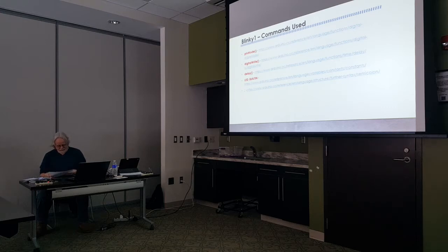Let's see if I can find these. You see D13 out there somewhere. I think it is PB5. Yeah, there it is, D13. It's the bottom right on the board drawing. And so it's port B bit 5. And yet they call it D13, and they program it as 13. So again, that's why the secret decoder sheet.